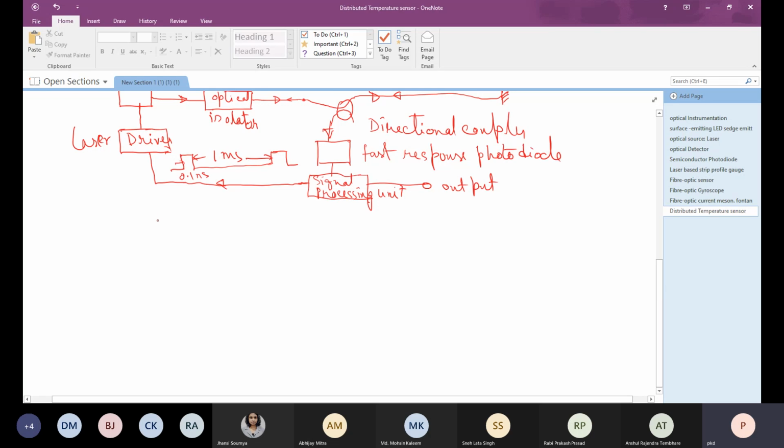So that means there could be a gating pulse. If I define it in, say, continuous time, the detector output will be I(t), and then there will be a gating signal, and this will be integrated over the time period of capital T, that is 0.1 nanosecond here. And then after that it will give the output.